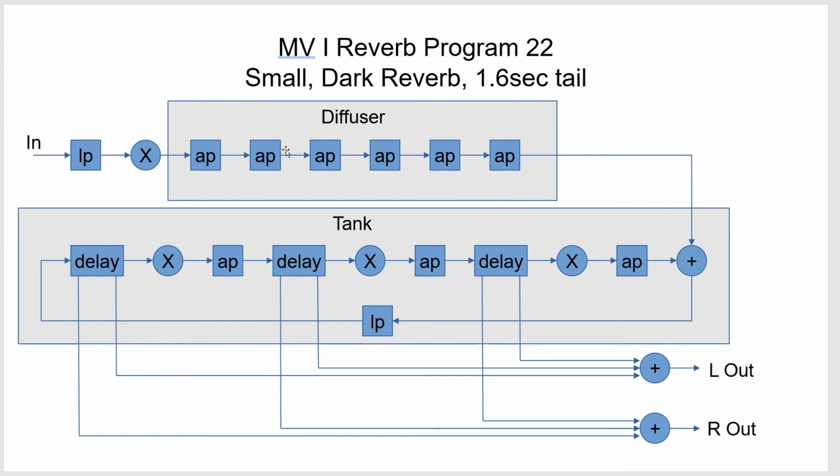These all-pass diffusers are fed here. So you can think of this output right here as having the original signal that's smeared in phase across a wide spectrum, and it's added to a series of 3 delay lines with their own all-pass filter diffusers. We call this a tank, and a tank is like a reverb tank with springs in it. So this is actually doing the main quote reverb effect, which is the decaying tail.